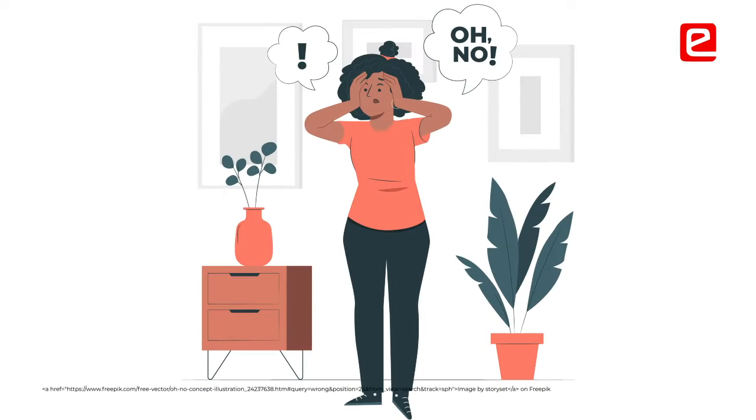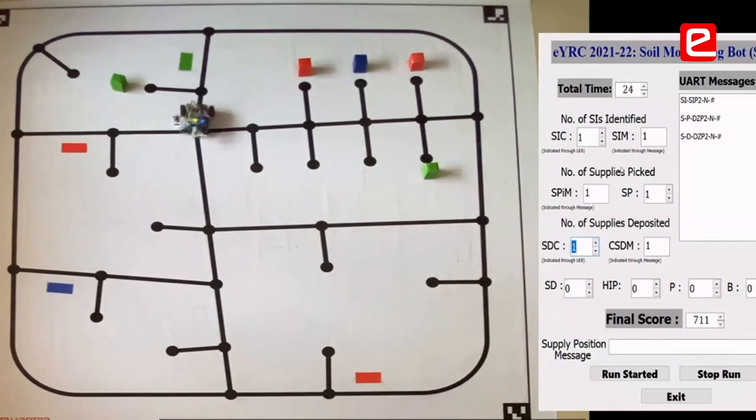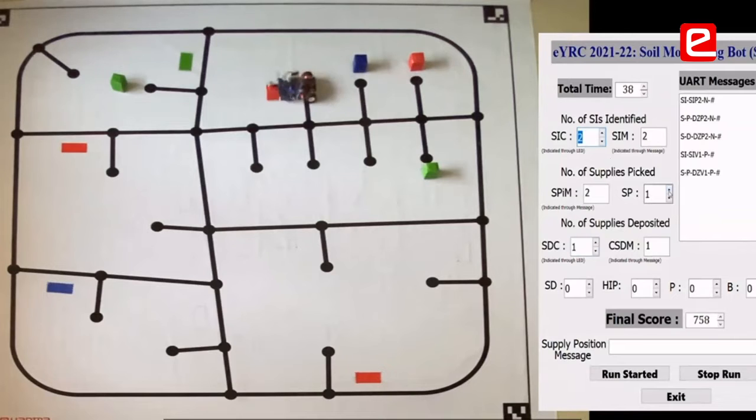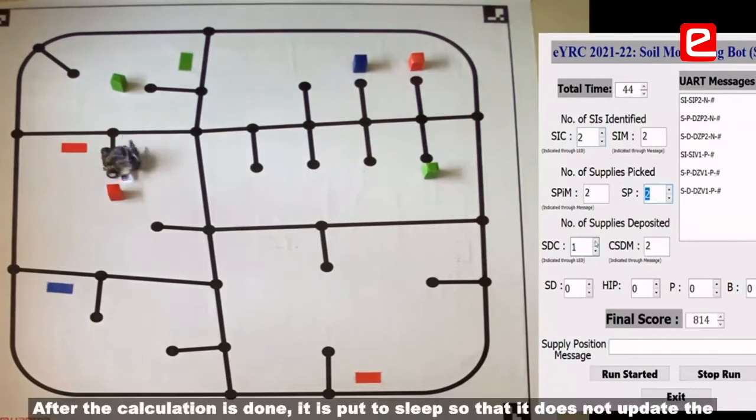So we realized that this is not the correct way, and also that having everything completed in a single clock cycle would put a lot of stress on the editor and the other parts of the FPGA compiler software. So we decided to use a state machine. Every state was covered in one clock cycle, so that gave enough time for the fitter and also made the fitter effort very low.